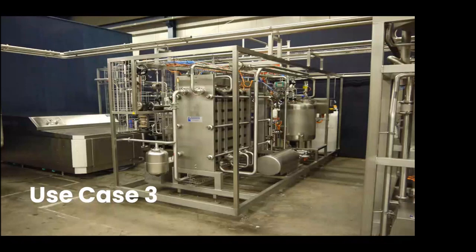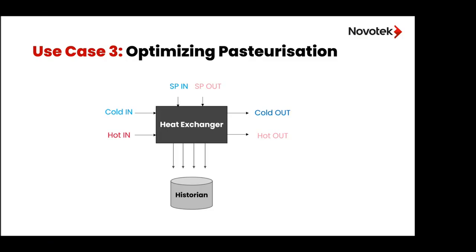This use case is situated at a pasteurizer machine. And of course, we simplified it a bit, but the principle is the same, that pasteurization is concentrated at a heat exchanger where two fluids actually have interaction with each other, transferring the heat. So we monitor the temperature of the cold fluids and the hot fluids going in, and the temperature of both fluids coming out. And with the set points, actually, we influence, we set the output temp, the desirable output temperature. All the signals are being logged into a historian. And once again, Cameron will demonstrate the advantage of a multivariable controller versus a standard PID controller.